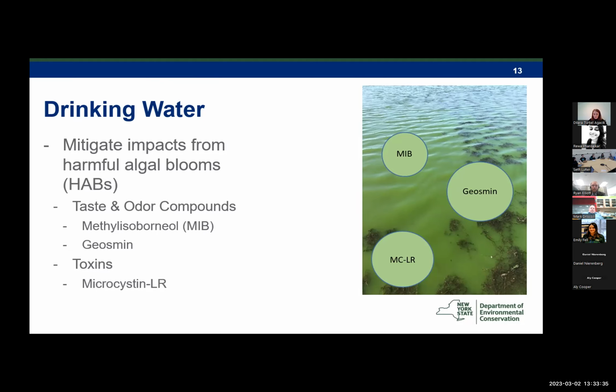And previous work by Dr. Driscoll, one of the PIs for Dilara's project, showed that a dose of less than 0.1 kilogray degraded all MIB and geosmin in a water sample, with no degradation products detected using gas chromatography with tandem mass spectrometry with solid phase microextraction. And a dose of less than 0.5 kilogray degraded all the microcystin LR, and there was only a noticeable degradation product detected at 0.1 kilograys using ultra high performance liquid chromatography with tandem mass spectrometry.